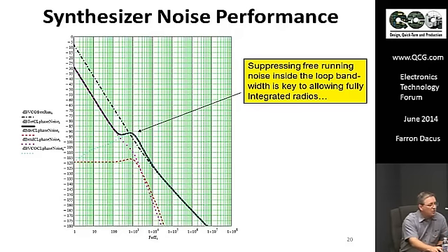And then once you put it in the loop, you will get some changes. For good quality VCOs, the resistors in the loop filter generate enough noise that you'll see them. If you have 1K ohm resistors, that's enough thermal noise to degrade a high quality VCO. Noise on the power supply will come through as well, because both the power supply and the input noise modulate the VCO, and that modulation shows up as phase noise.